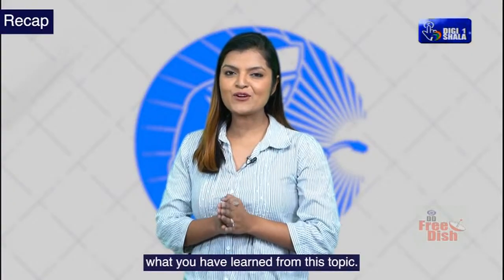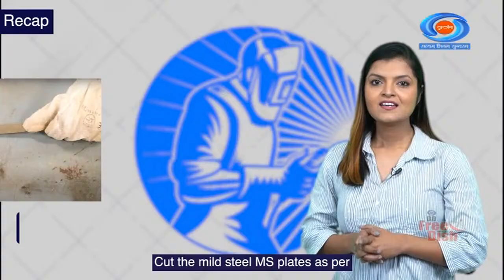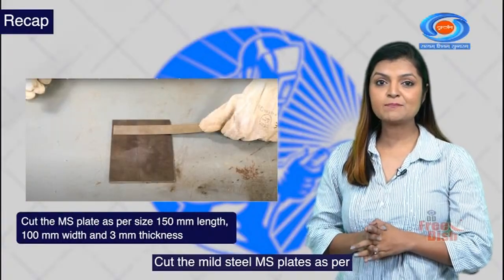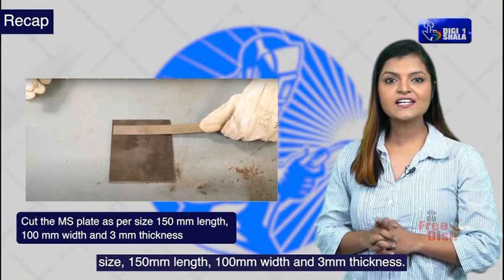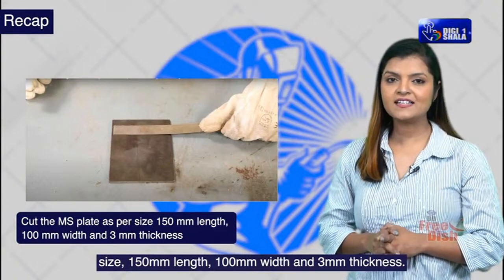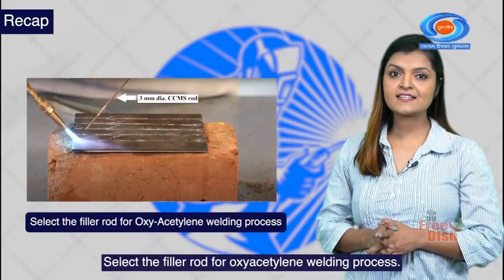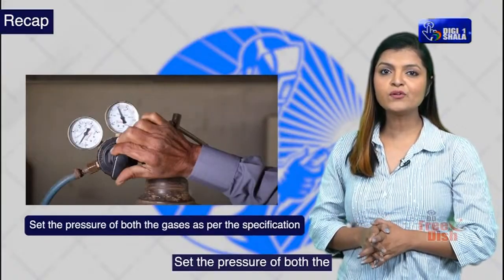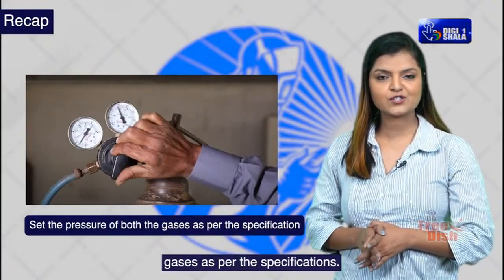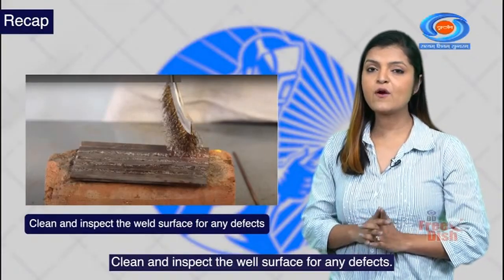Recap. Let us do a quick recap of what you have learned from this topic. Cut the mild steel MS plates as per size 150 mm length, 100 mm width and 3 mm thickness. Select the filler rod for oxyacetylene welding process. Set the pressure of both the gases as per the specifications. Clean and inspect the weld surface for any defects.